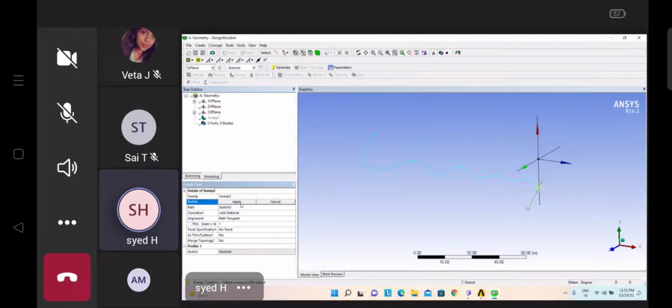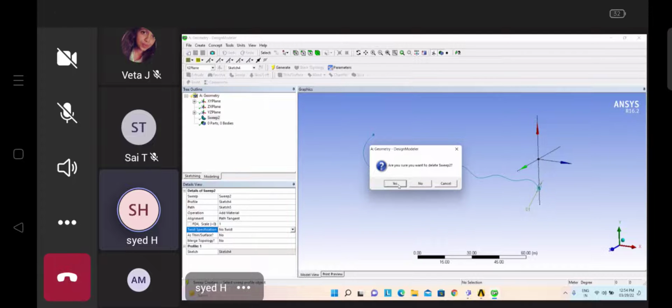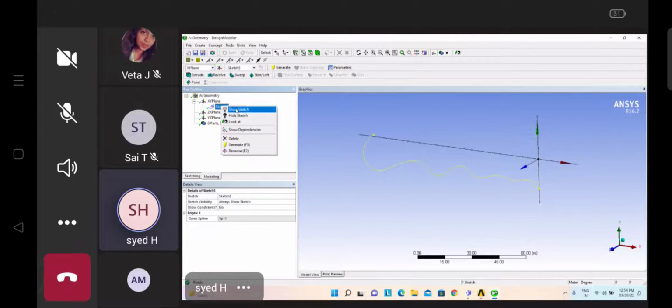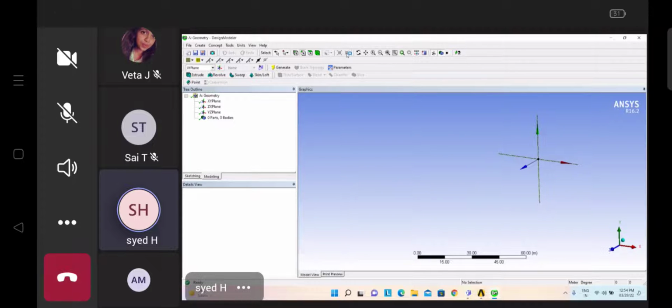Okay. The next thing here is twist. If you want to make somewhat of a twist, you can specify. So right now, suppose for example, if I want to create a spring, for a spring we definitely require a helix shape. But right now I don't have any helix. So in that case, what you have to do is, directly in the sweep command, it gives that option to you. In the sweep command directly you can find that option here.